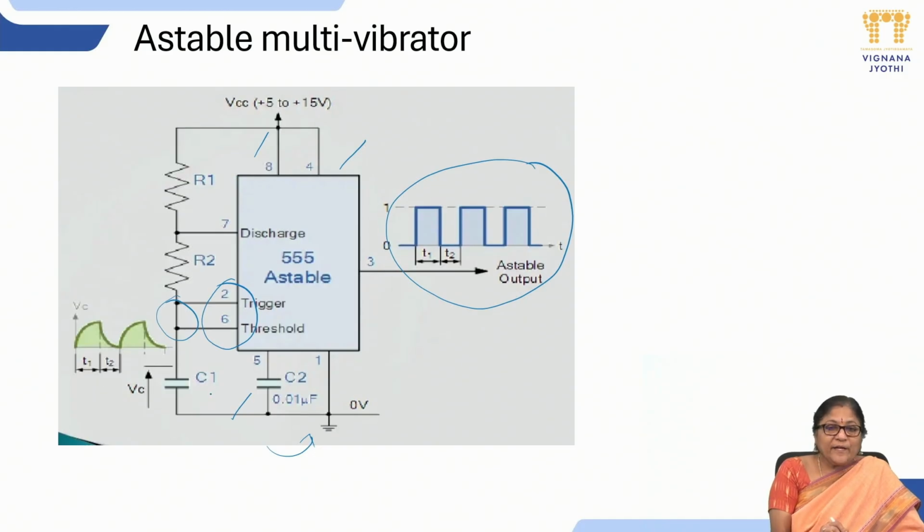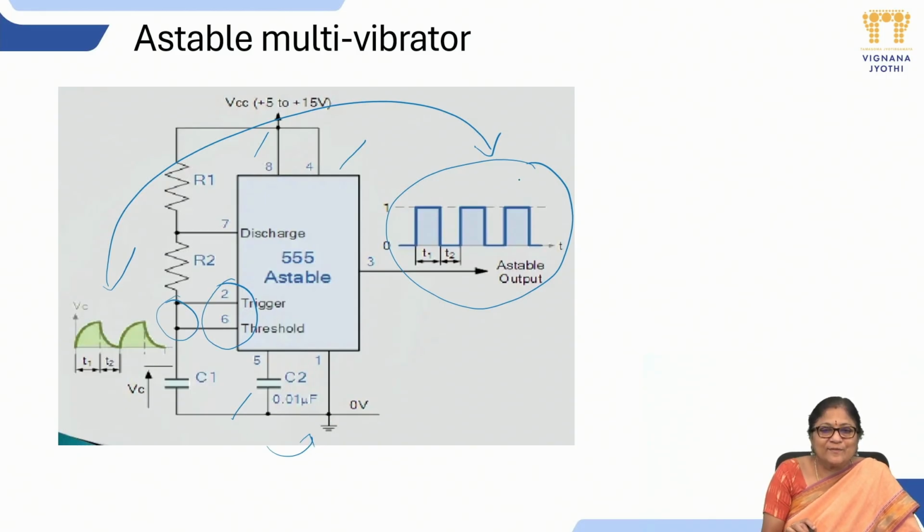So then we have to make this capacitor charge to a certain extent by making your internal transistor turn on and off, so that we can make this capacitor also discharge. If you look at the charging and discharging diagram of your capacitor, it produces an output like this. As soon as you power up between pin 8 and pin 1, like power supply and ground, it starts producing oscillations and it never stops. That's why it is also known as a free running multivibrator.